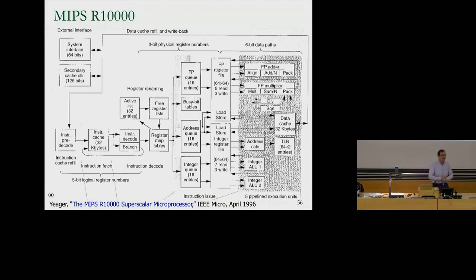They quickly figured out that it's very low performance. This is one of the latest MIPS designs. You can see that it's very heavily out-of-order execution. So forget about interlocking. They added a lot of hardware to make it high performance, because it was not easy to have simple hardware and get high performance out of it. You just cannot deal with these long latencies and variable latencies easily in the compiler. That's why the vision said there should be very little hardware, not even support for interlocking.